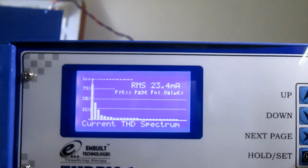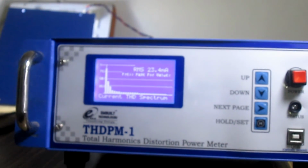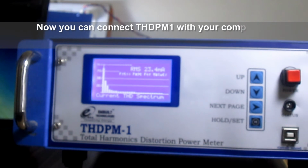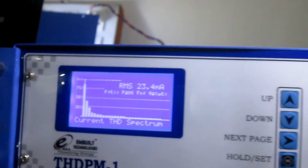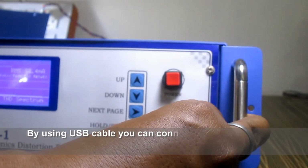Now I would like to transfer all this data to the laptop automatically without noting it down manually. I can do that using the USB port provided on the front. This is an optically isolated USB port so that the electrical circuit inside the THDPM1 is isolated from the computer. It is a safety feature.